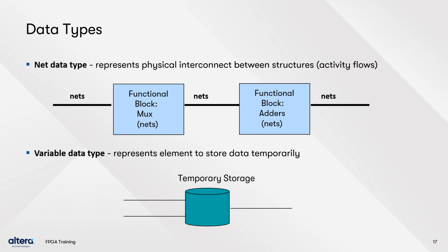Variable data types are used to temporarily store data. They are similar to variables in other languages. Variable data types may be synthesized into hardware flip-flops or registers or combinatorial nodes depending on usage.